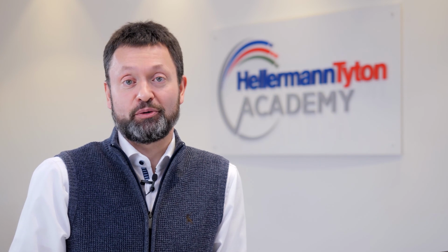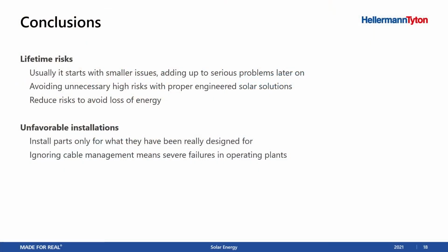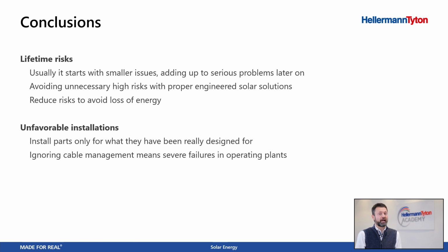And to sum up the unfavorable installations, there are some parts that are misused for their application. Make sure that you use only parts that have been designed specifically for this purpose. If you ignore cable management, as a final word, the plant is going to fail. Make sure to implement proper cable management. Make sure the connectors are not touching water in any case. Make sure the sun is not touching the connector in any case. Make sure that all this is going to work out. And then you have very low operation cost over the operation of your plant.